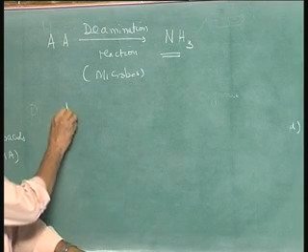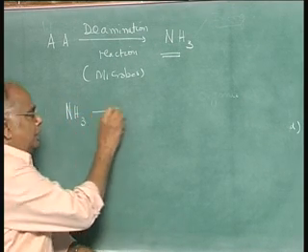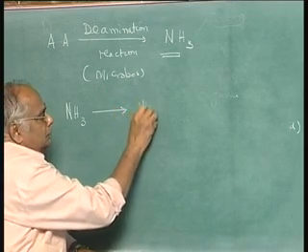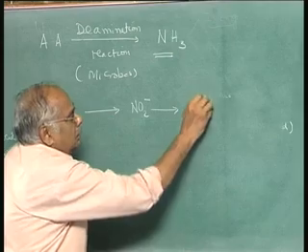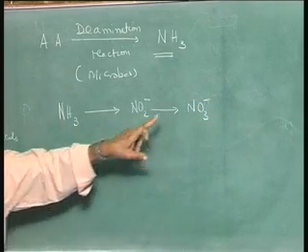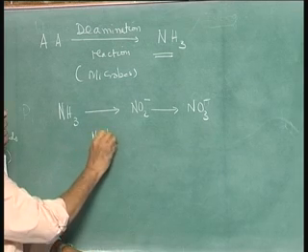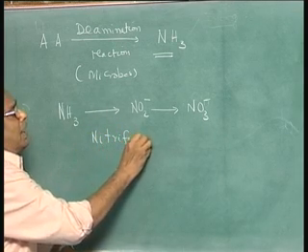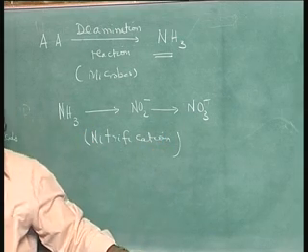The ammonia which is present in the wastewater is converted into what is called nitrite and then goes to nitrate. That is, ammonia is oxidized to nitrite and to nitrate. So, this step is known as nitrification, and nitrification is carried out by microorganisms.